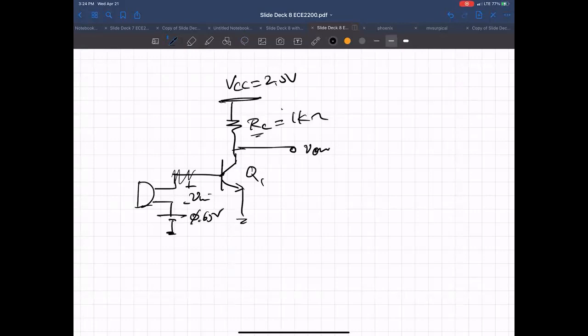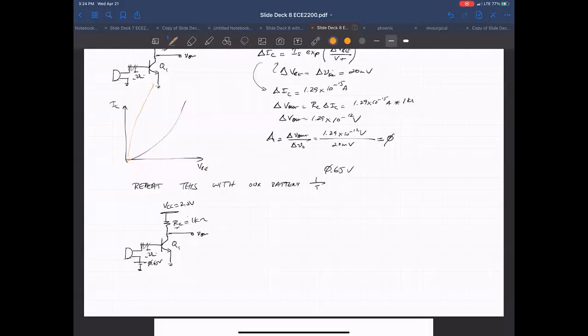And what in effect that does is, the orange represents the biasing level here, and then the red is going to affect this biasing level. So let's say it puts it somewhere out here, 0.605 volts, and we're biased here, where we might get a bigger change in collector current.